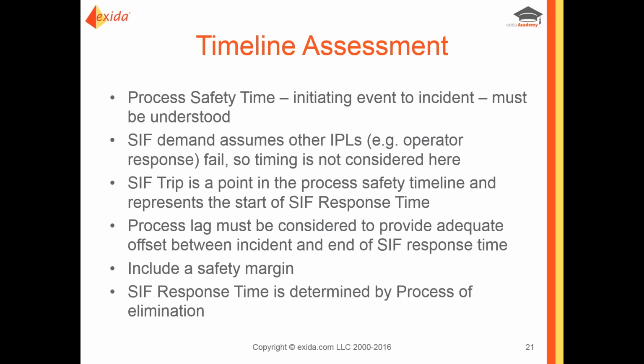One big part to consider is the process lag. If the response is something like turning off a valve and flow immediately stops, then the process lag may be almost zero. But if it is, for example, a chemical reaction where we're introducing a quench material, we have to allow time for mixing, and time for the reactions to occur to quench that overall runaway reaction, then there might be a pretty significant process lag.